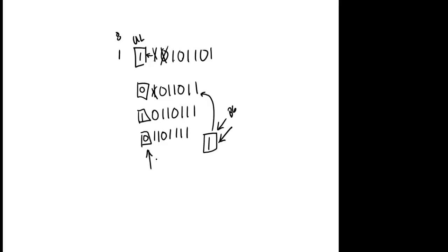What would happen if my shift bit was specified as the unload bit? What if I told it my shift bit was my unload bit? It would change all the time. Or we shift it right? It would do what we call a roll or rotate. It would rotate left. Y'all understand what we just said? The shift bit was my unload bit. So let's say we start off with the unload bit being a 0, and I started off with this right here.